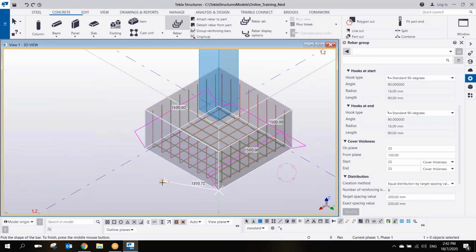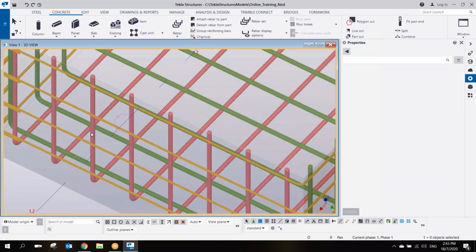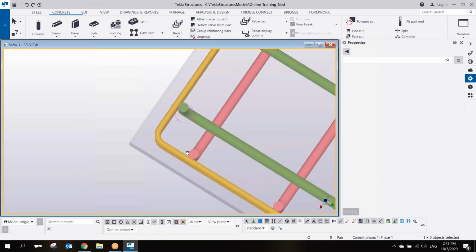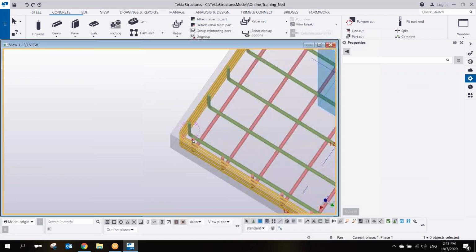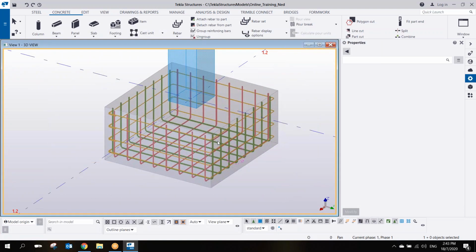Since I'm doing a close link, I also pick the first pick point again, pick point 5, and then middle button of your mouse, and then the range is 1, 2, and there you go. You have now the close link here. Can you try that one, close link?